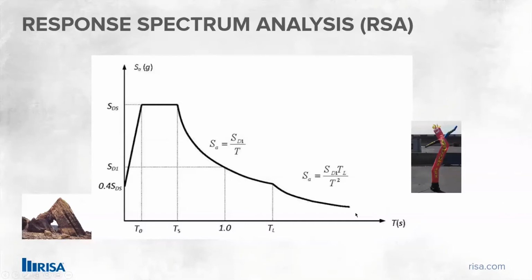And on this end over here, you can see that since it's so soft, it's like it's isolated. The upper structure wasn't actually affected by the seismic excitation much. And between these two periods, you've got a peak here, which represents the structure period, which is close to the major period of the excitation. So a resonance happens.